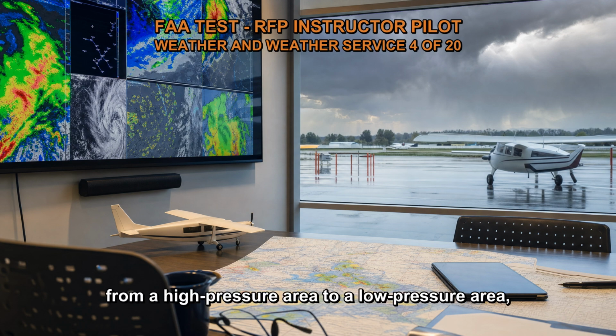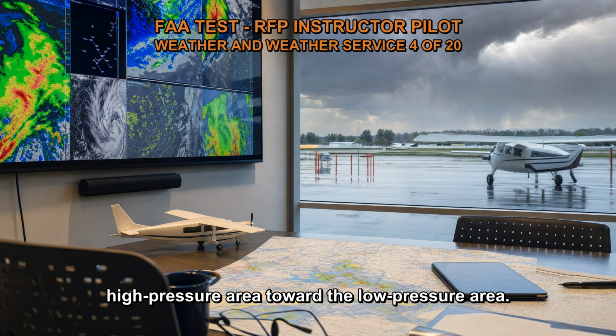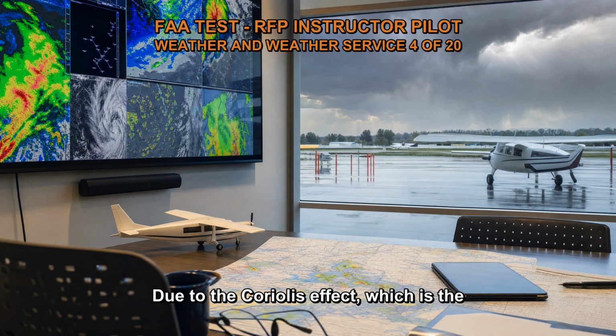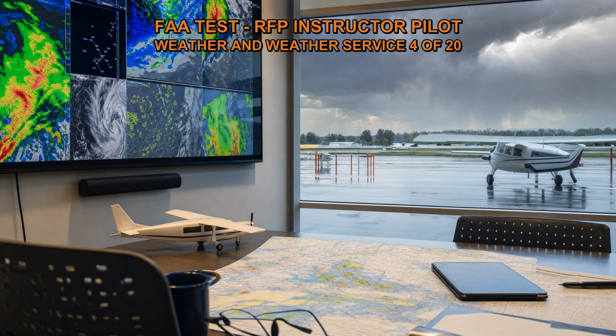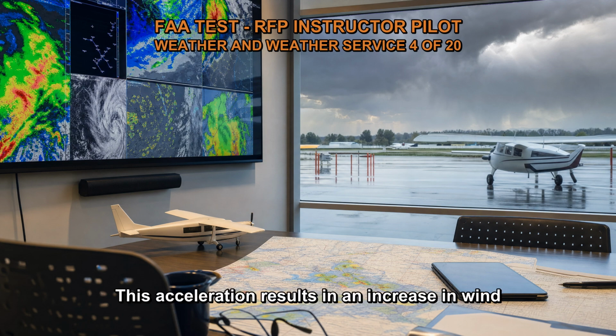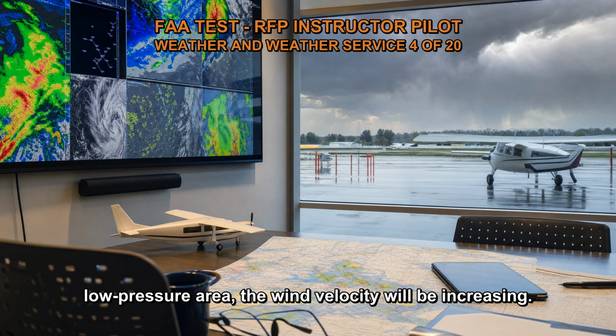When flying from a high-pressure area to a low-pressure area, the pilot will be transitioning from an area of high pressure to an area of lower pressure. The air will tend to flow from the high-pressure area toward the low-pressure area. Due to the Coriolis effect, which is the deflection of moving air caused by the Earth's rotation, the wind direction will appear to be from the left of the pilot's heading in the Northern Hemisphere. Wind speed. As the air moves from a high-pressure area to a low-pressure area, it accelerates due to the pressure gradient force. This acceleration results in an increase in wind speed. Therefore, when flying from a high to a low-pressure area, the wind velocity will be increasing.